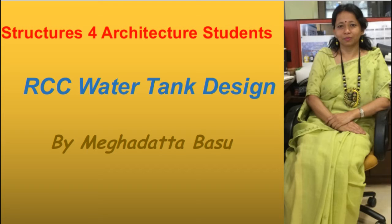Now, if the joint between the wall and the bottom slab is flexible, that is a sliding joint, it will be free to move outward. So the hydrostatic pressure at the top is 0, and there will be no change in the diameter at the top. But the hydrostatic pressure at the joint at the bottom will be maximum, resulting in the maximum increase in diameter there, and hence the maximum movement if the joint is flexible.